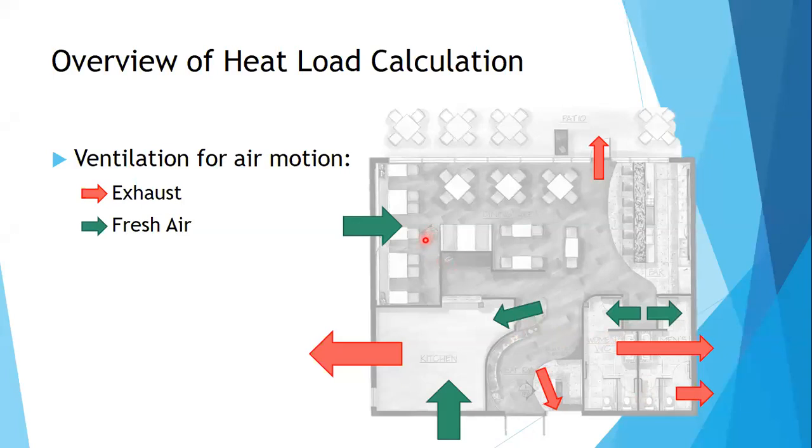Engineer Tadina's question is about positive ventilation and negative ventilation. Example, this green arrow, this 70 cubic meter per hour. Let's say I did not put any fan here. Let's say I just put a wall opening here. And I put a fan here at the exhaust air. So here there's a fan, here there's a fan. Meaning there's a fan here exhausting out 100 cubic meter per hour. There's no fan here. Because of this fan sucking out 100 cubic meter per hour, this space becomes negative.